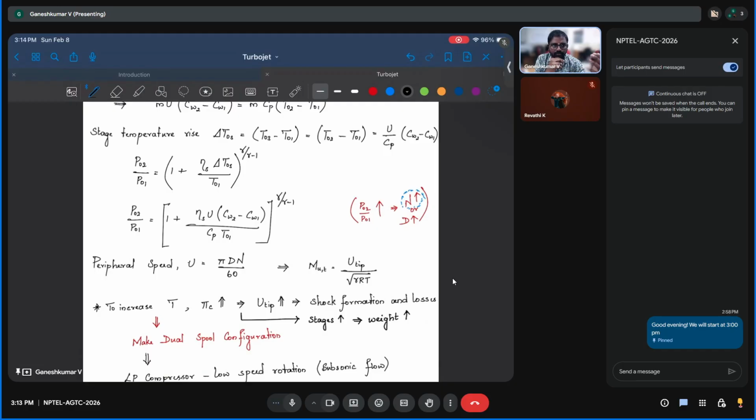It could choke the flow and lead to supersonic flow inside the compressor itself. In those locations you will form shocks, and it will lead to a lot of losses, and it would be fatal to the blades. So that's why people actually went from a single-stage to a multi-stage compressor.